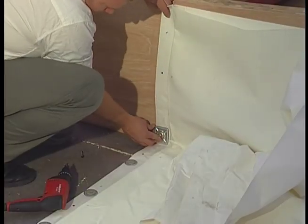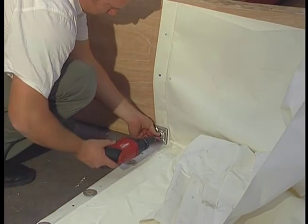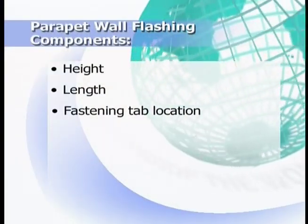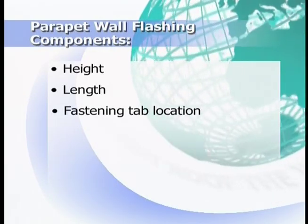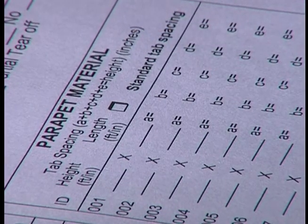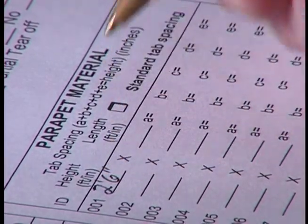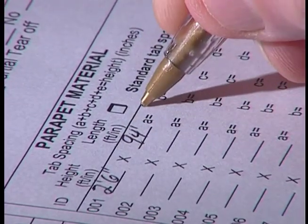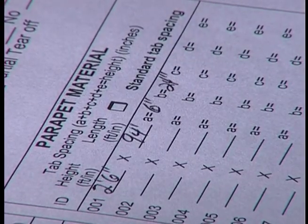Duro-Last custom manufactures flashings to cover all or any part of parapet walls. All parapet wall flashings must contain a tab. Parapet wall flashings have three components: height, length, and fastening tab location. The height and length are the overall dimensions of each parapet section. Tab locations are denoted by the letters A, B, C, etc. These letters denote the distance between fastening tabs. In this example, the parapet roof section is 2 feet 6 inches high, 94 feet long, and the tab locations are at 6 inches on the deck and 24 inches up the wall.